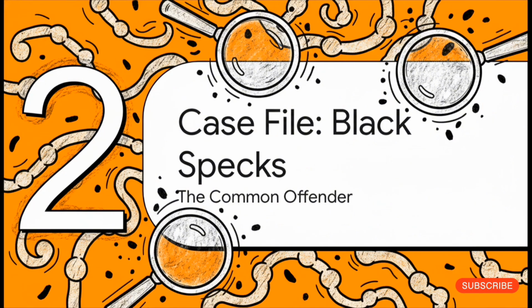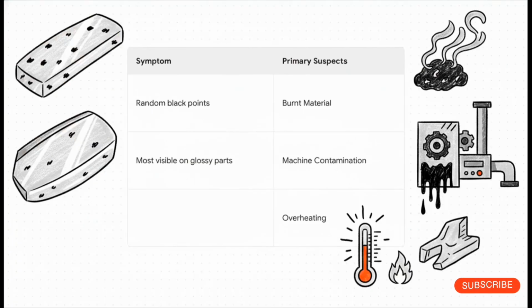All right, detective, let's open our first case file. We're looking at one of the most common offenders out there: black specks. Those tiny little dots that can completely ruin an otherwise perfect product. So, the evidence is pretty clear. You've got these random black points scattered all over the part, and they're especially easy to see on high-gloss surfaces. The primary suspects? Well, it's almost always related to material degradation. You've got burnt residue in the barrel, some kind of machine contamination, or you're just running the process way too hot.